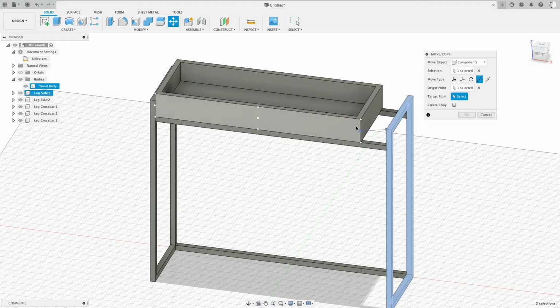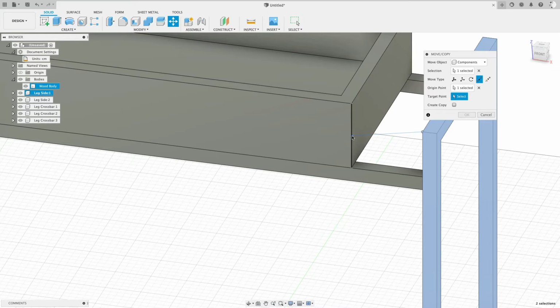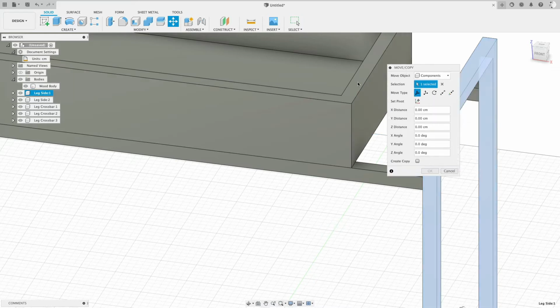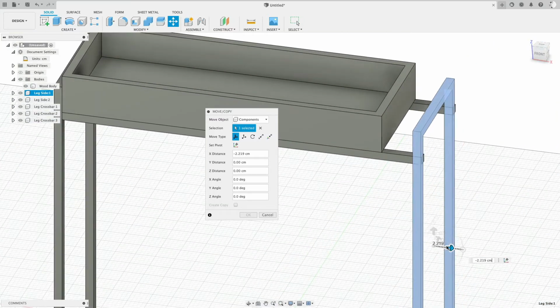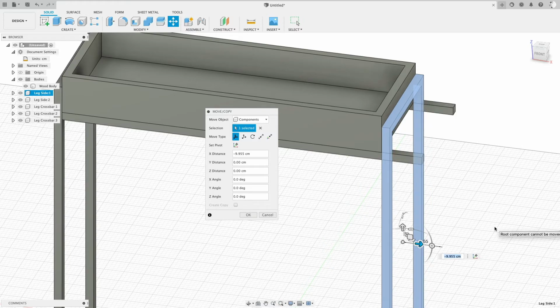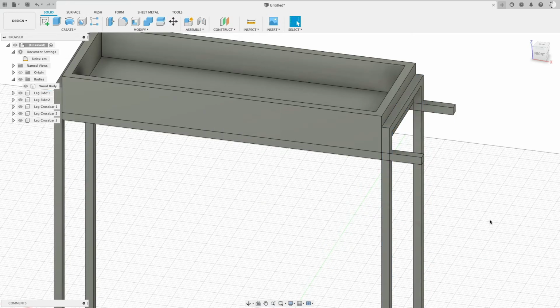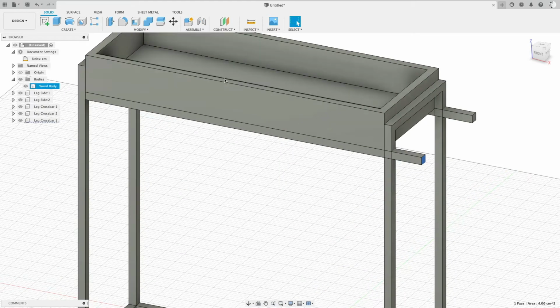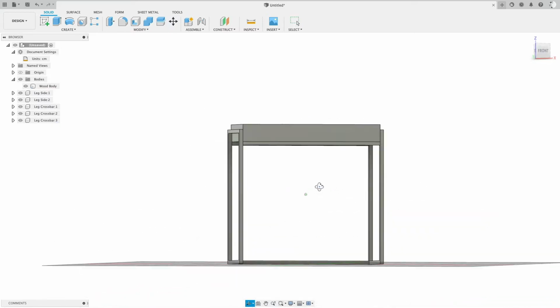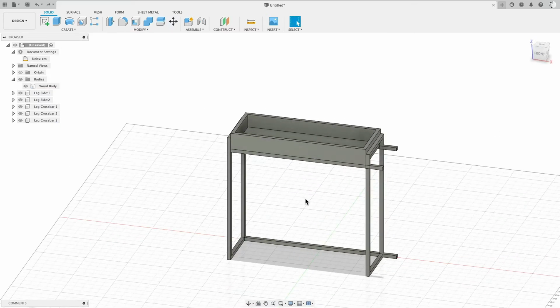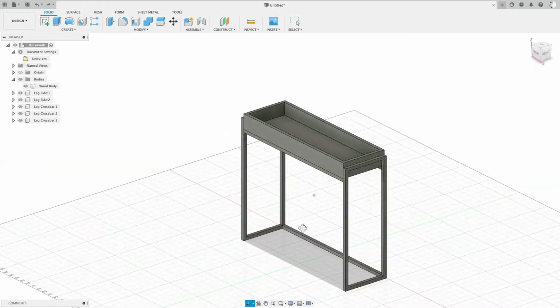You see the snapping is a little bit tricky. So this move point to point is not going to work as well. But because I moved this by 10, I just moved this also by -10. So that works. And now here I can select base point to point and say from here to, I have to be careful to select the correct point there, and you see all the other components moved with it. Beautiful. And then we'll undo all these steps.